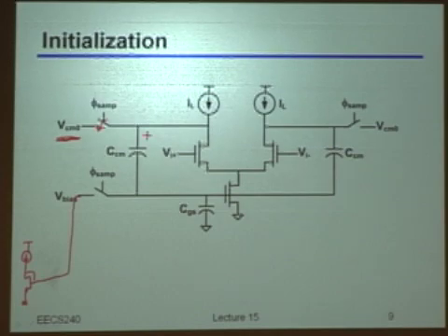So I would like, indeed, to charge this capacitance to a voltage that is VCM0 minus V bias. That's what I would like. And I can do that when the amplifier is not active, right? Then at this point, I'm basically okay, because when I don't need it, right?